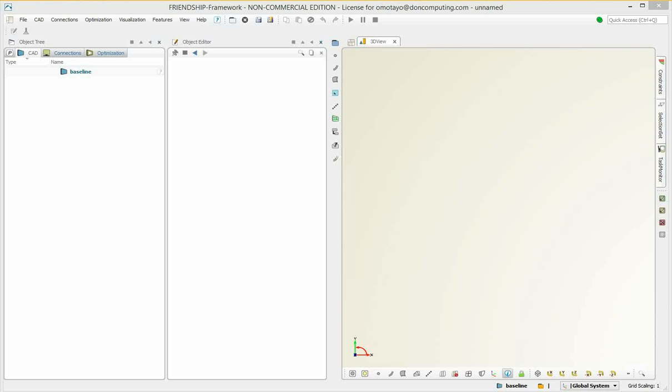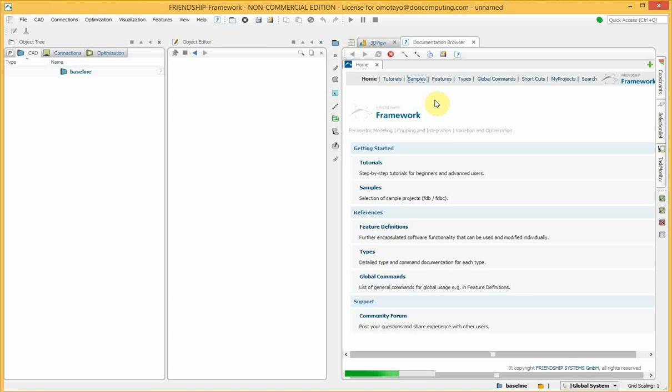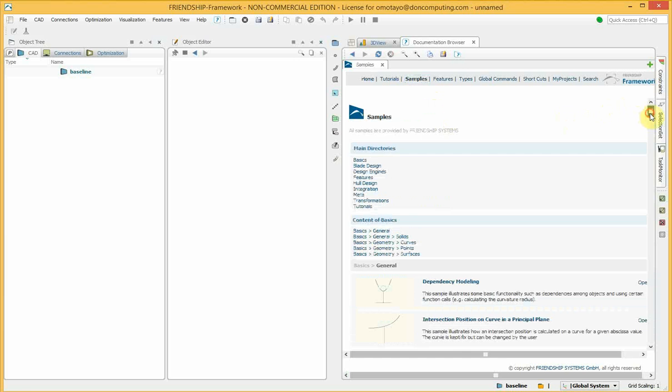We will use the contour curve from a previous tutorial. It generates 2D shapes starting from a circle, and ending as a rectangular shape. A prepared sample is available from accessing Help, Documentation. Then clicking Sample and scrolling down to 11 Parametric Contour, and opening the sample.